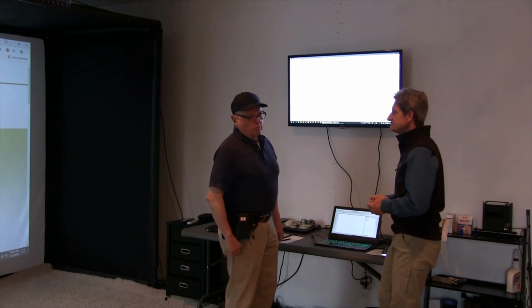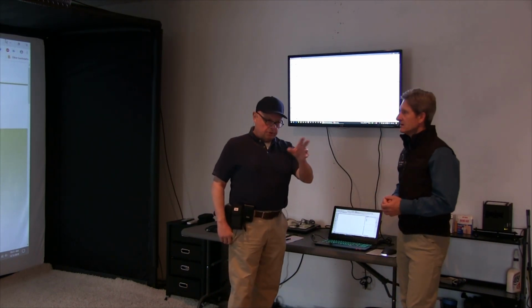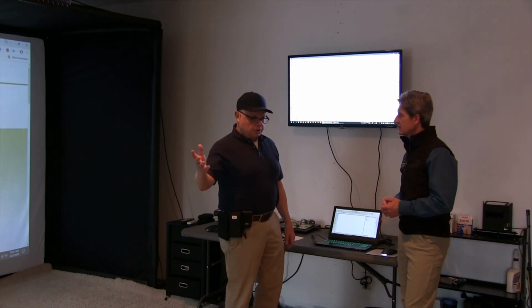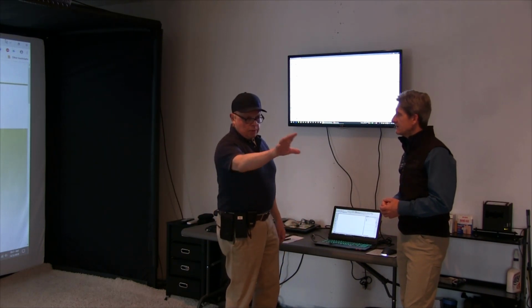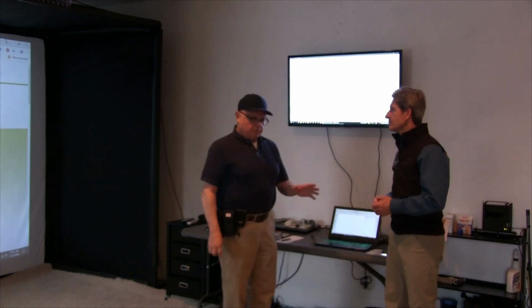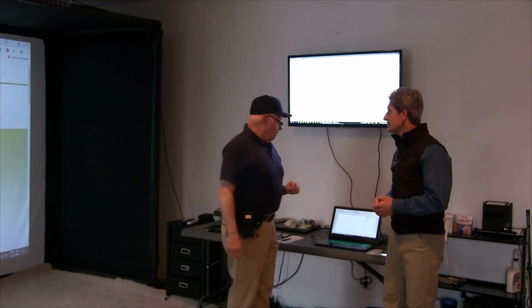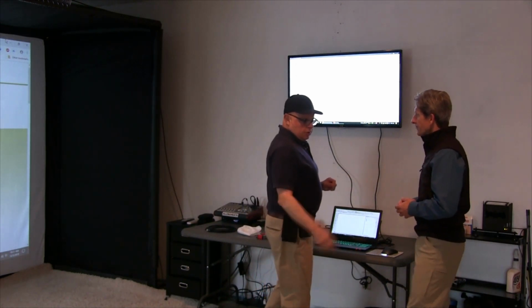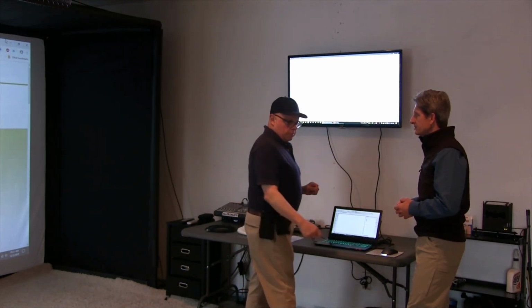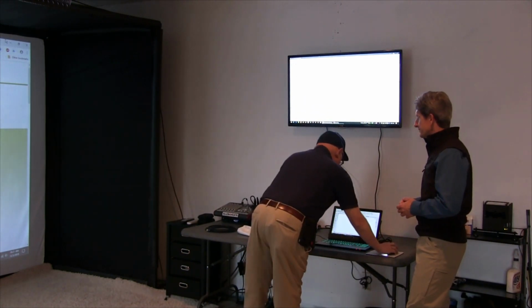Okay. Well, with this room, I know that the walls are going to be 2x6. I can see that it's a siding, so I'm going to set up the wall type for the exterior as a siding 6 wall. Okay. I'll worry about the actual size of the material shortly. That doesn't have to be done right this minute. Okay. So the first thing that I'm going to do is just draw the rough outline and the shape of the building as I see it from this point.